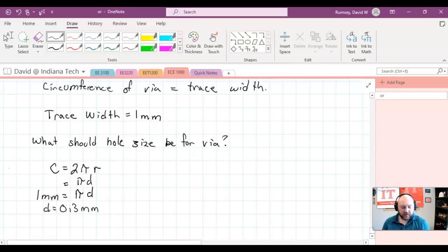And then we'd also want to put a copper pad around that as well. Again, there's not necessarily a specific set of dimensions for how much copper pad to put around the diameter that we've drilled, but you often are going to want that. We also have to be careful sometimes, because if you do that, you can etch out something you don't want etched. We'll talk about that when we go through the design here.